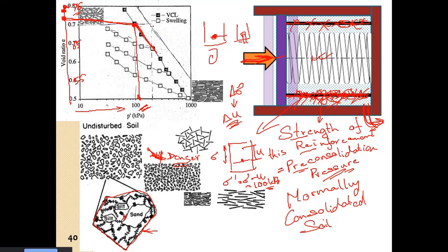Now if we revert back, if the soil had behaved like a spring, it would have been in this manner. But it is not a spring, it is a soil, and therefore the densification which it had received, the consolidation which it has undergone, will be stored in the soil, and it will revert back through this path.